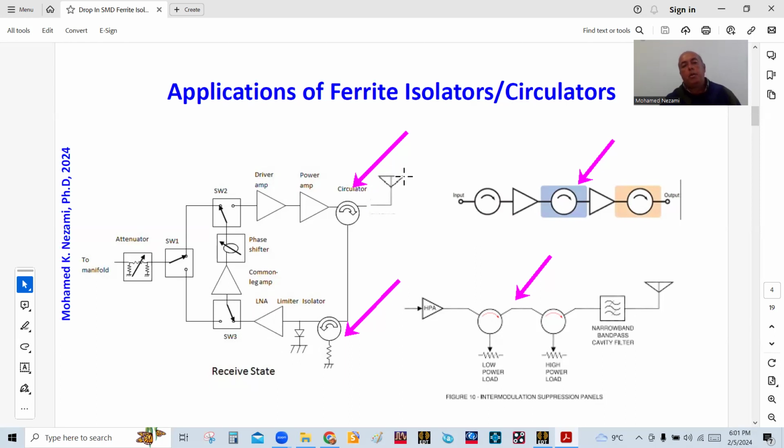So this is a circulator with one terminated port, meaning it's an isolator, for the LNA, the low noise amplifier. And then on a receive path, the signal comes in here, it can't propagate that way. It goes this way onto this, and it goes this way and into this. So the combination of the isolator and the circulator in here is a perfect transmit receive duplexing system.